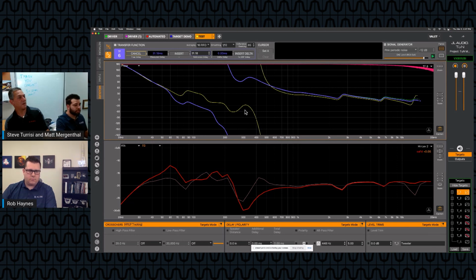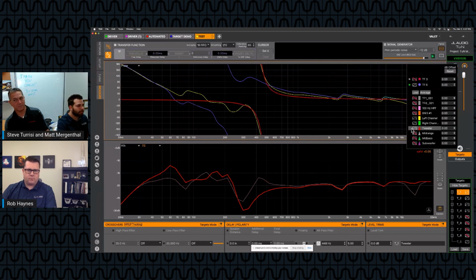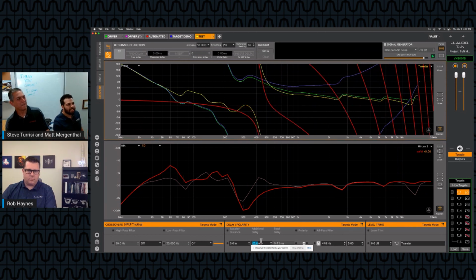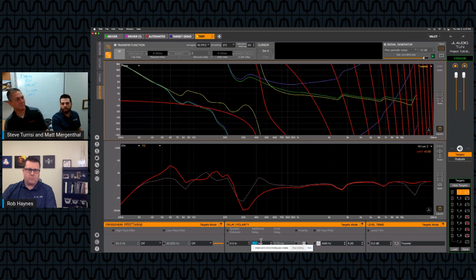So just so you know, it doesn't matter how many wraps are on a given channel, right? So let me bring up the tweeter channel, for example. When I click on this tweeter channel and I start adding delay, you see there's more wraps. The wraps are relative to the other drivers. Correct. So as long as the other drivers have the same amount of wraps, it doesn't matter. Obviously, more wraps make it a little harder to see the data.